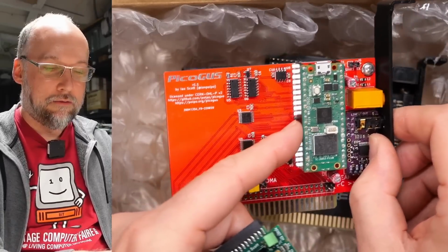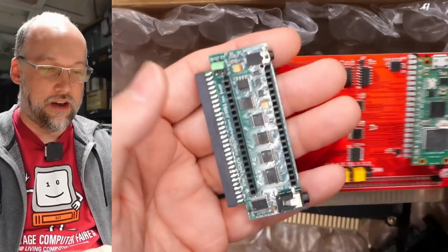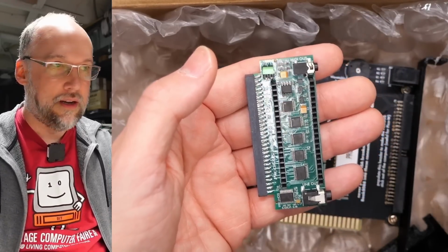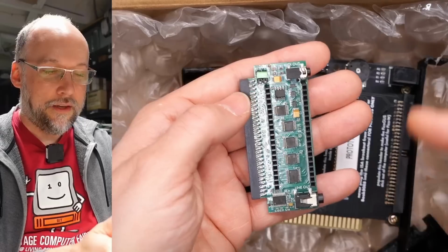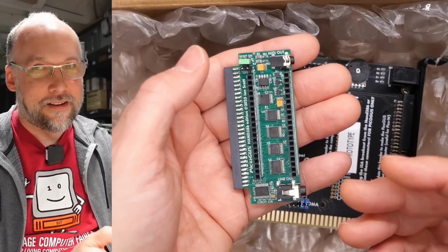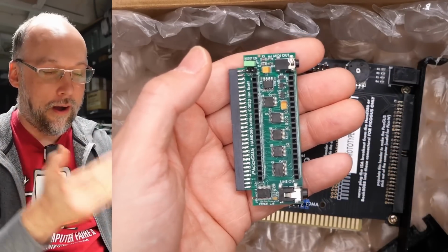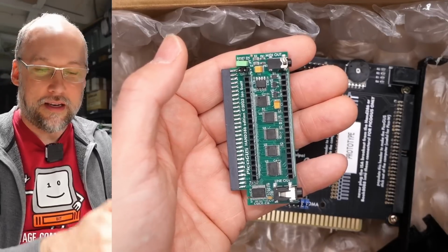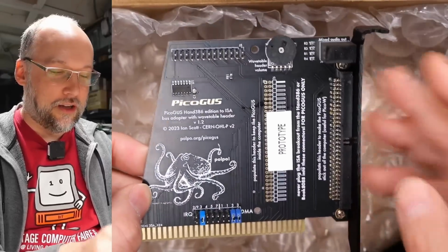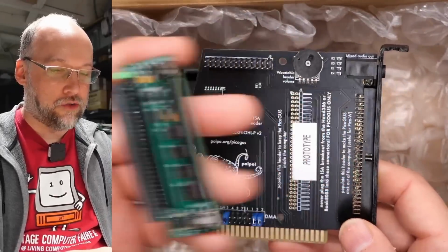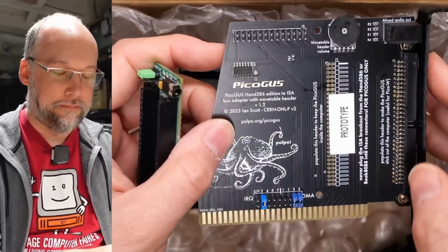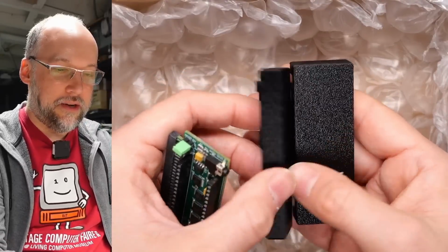You take the Raspberry Pi off of this board, or you just get another one, plug it into here, and this has all the same functionality as the regular PicoGUS. You have MIDI output and you have sound output on this as well. You're basically giving that little portable funky computer full-on GUS compatibility in something that is super inexpensive. This board here is simply just an adapter from the Hand modules, which have a connector just like this, to a regular ISA bus. And then Ian included a little 3D printed case.